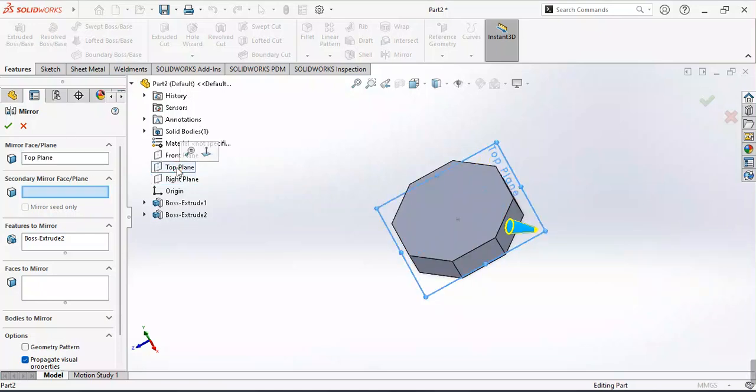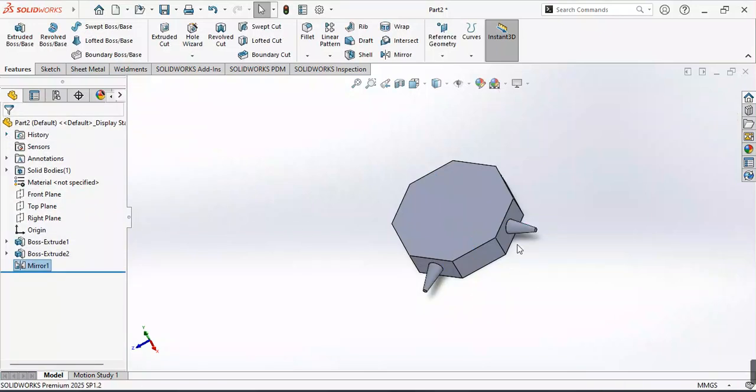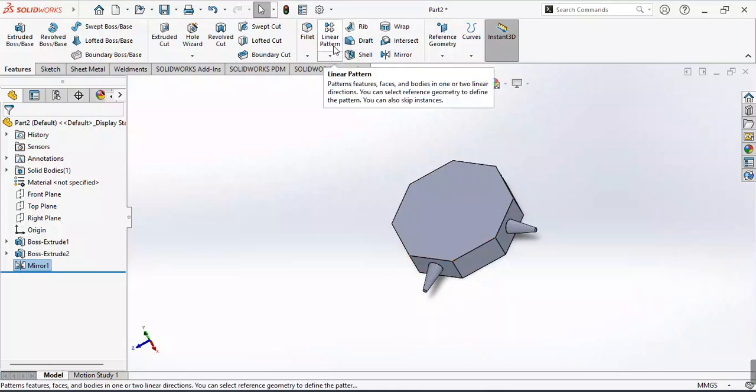If you choose this plane, it won't mirror because there is nothing at the top. Okay, so that's how you know. You can pick, let's say you pick flat, you see that this object is now here. So if you click OK, you can see that this guy has come this side now. Okay, so that's how you can use these linear patterns.